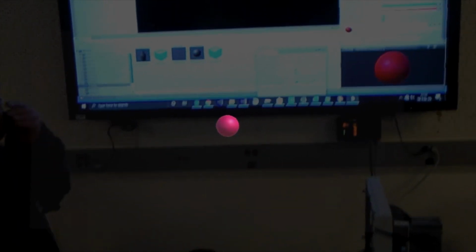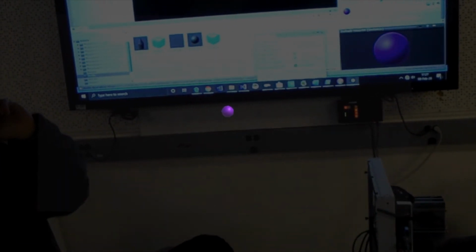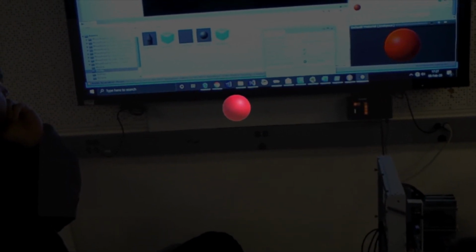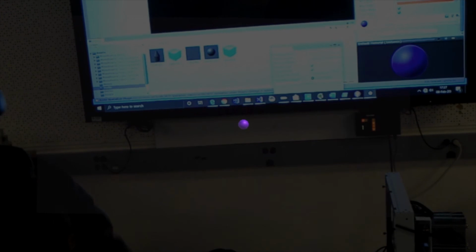Given a min and max value that the sensor could possibly have, we calculate a percentage. Based on that percentage, the sphere will resize or recolor itself as a way to show a change in the sensor's value. Each sensor is labeled with a preset sensor name and displays a live value above it.